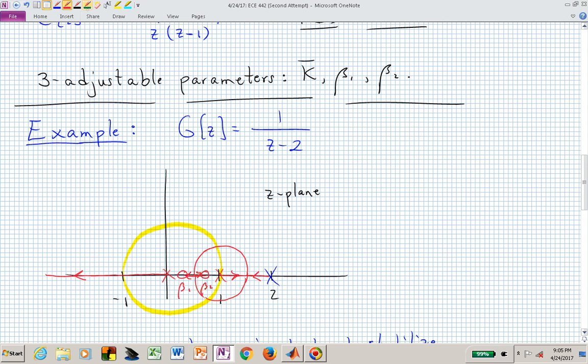And I hope it's clear that we will be trying to generate maybe closed loop poles. The idea then is to get 3 closed loop poles. There are 2 of our closed loop poles, and we hope that the third pole stays inside the unit circle,